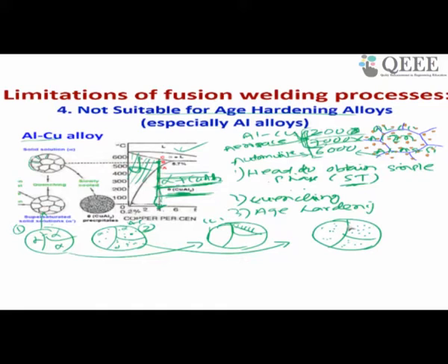Now the dislocations are moving from one grain to another grain, and in between there are microstructure precipitates. These precipitates are hard particles. So what will happen? Wherever precipitates are there, they will obstruct the dislocation motion. As a result, the dislocation cannot move further.